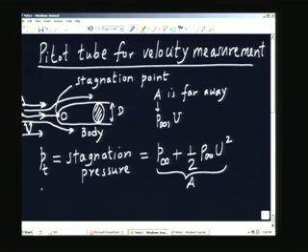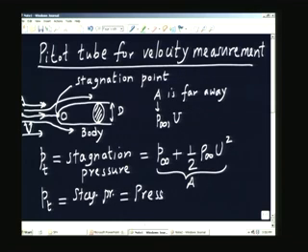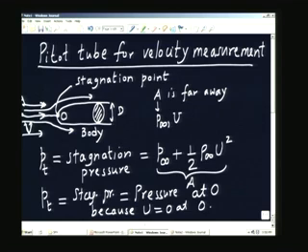And at O, again stagnation pressure equal to the pressure at O, because u equal to 0 at O. When u becomes 0 at that particular point, the pressure goes up because the total pressure remains constant. I am assuming ideal fluid flow, that means there is no friction and other things are ignored, because we will later see how to account for them. So, the total pressure or the stagnation pressure given by P infinity plus half rho infinity u squared is the same as the pressure at the point O.